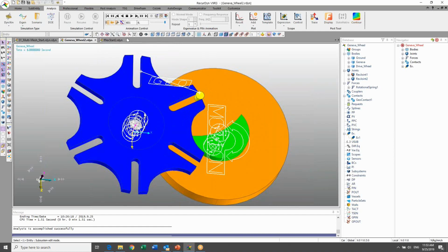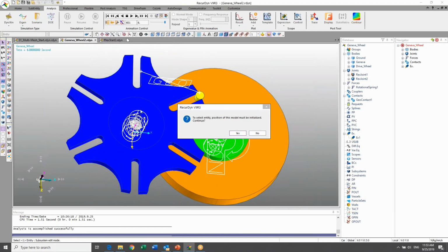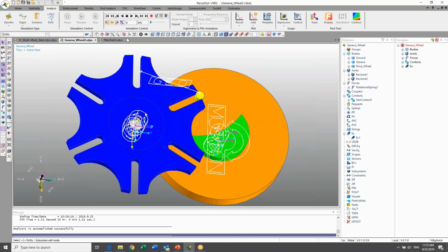And we're also trying to preserve this joint here. There's a revolute joint and a spring, which is, I believe, just a damper at the moment. There's no spring force, it's just a damper. And so we want to go ahead and include all of those. We want to preserve the contact, preserve the joint, preserve the spring damper there, and mesh it.